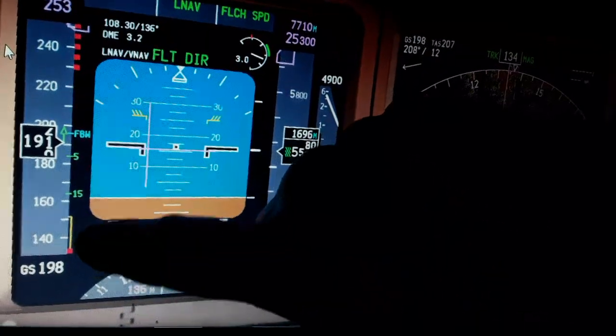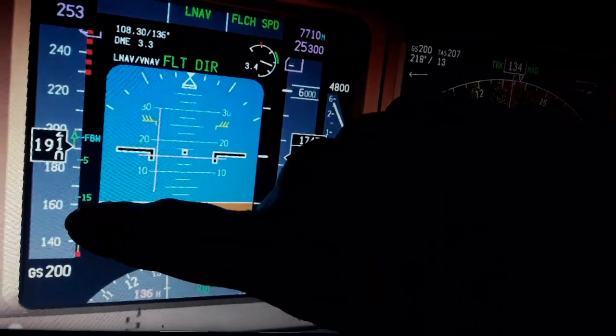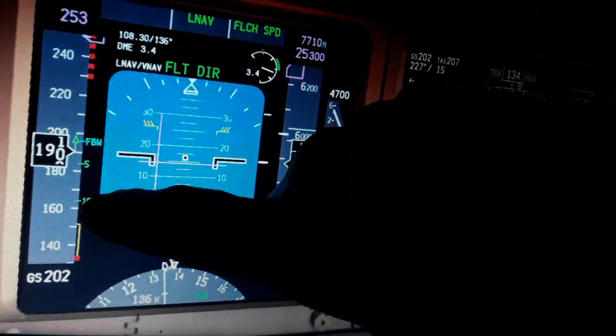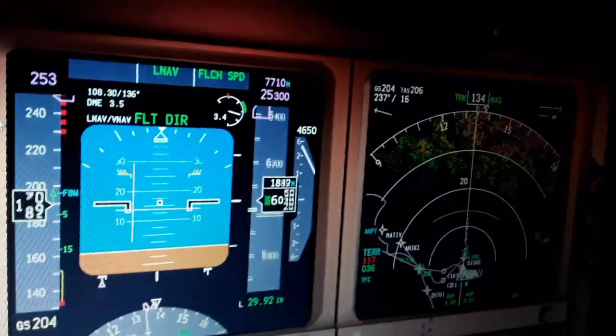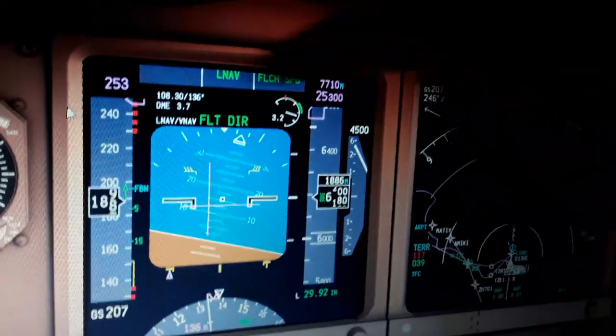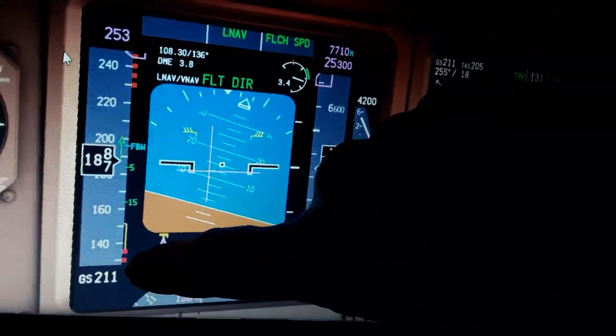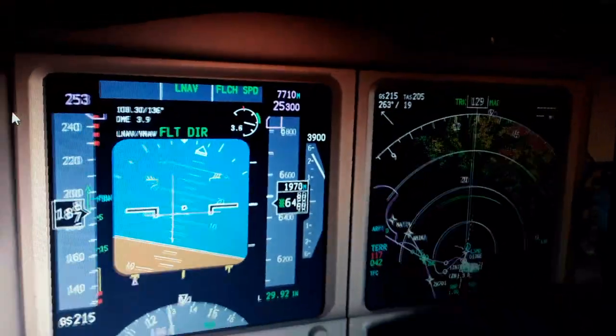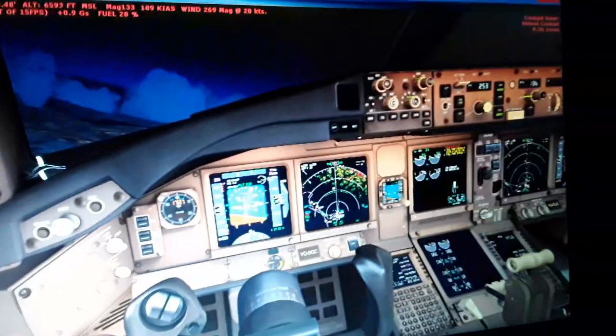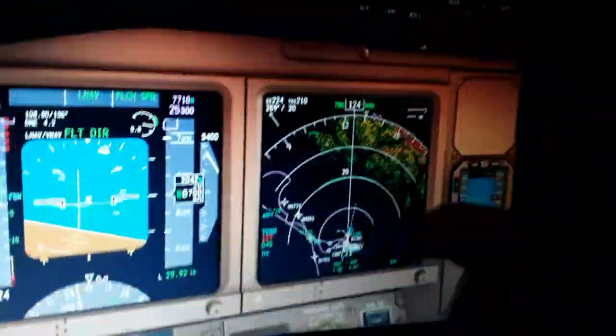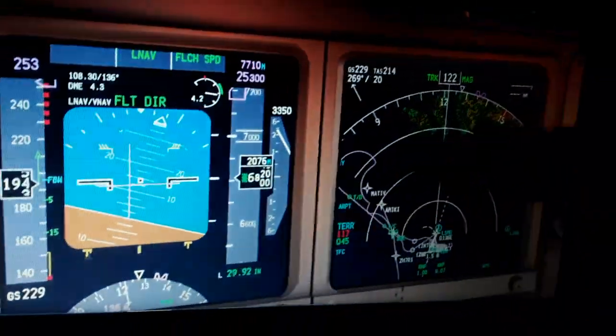You can see the stall speed, the yellow and the red margin. We need to avoid it, because the aircraft is going to start falling. We have the flaps limits, also the red marking here, and the red is the stall speed. So we have the navigation here, the terrain, we have the waypoints, we have to follow the route. So we keep climbing like that.